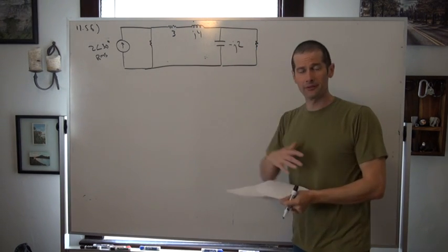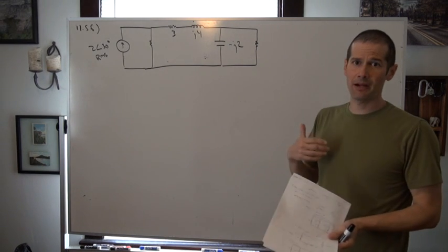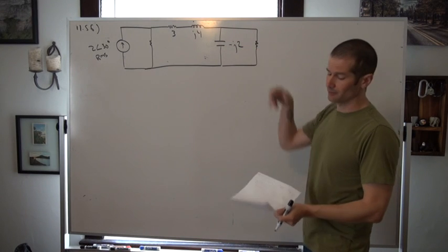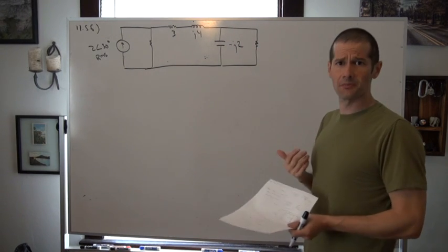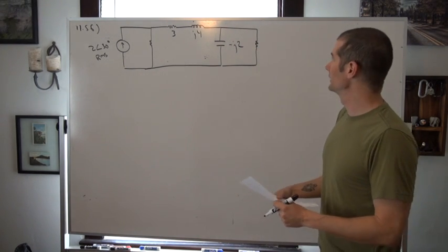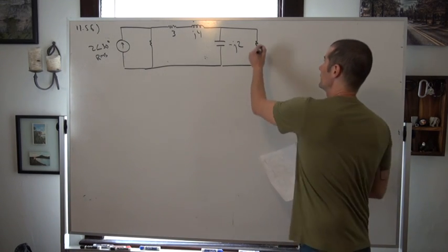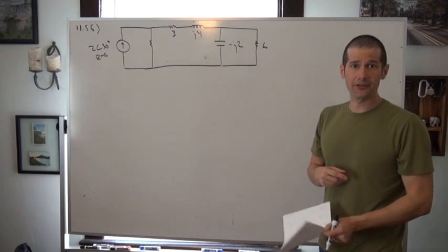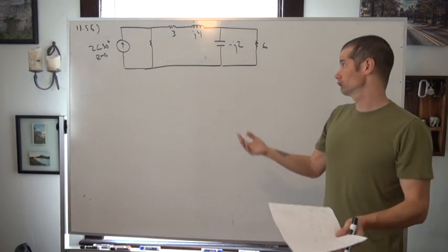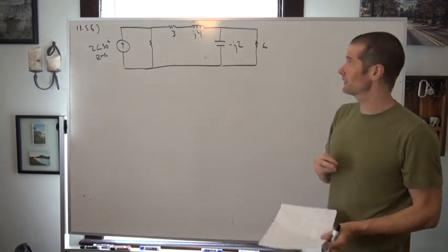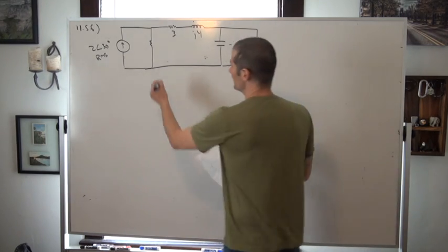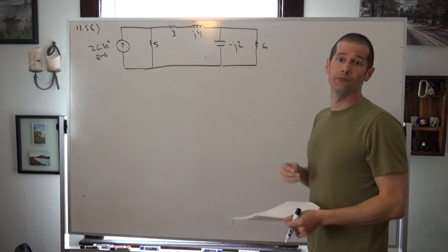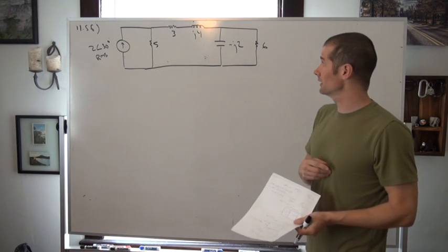So for this one, if we wanted to find basically the complex power that's being supplied by the source and delivered basically to all of our impedances here, this one's super simple, because all we have to do is simply, oh, we had a 6 ohm resistor right there, just find the total equivalent impedance that the source would actually see, and then actually take the voltage that we would actually get from that. Oh, we also had 5 ohms right here, getting too excited. And then basically just go ahead and simply make our calculation of complex power.